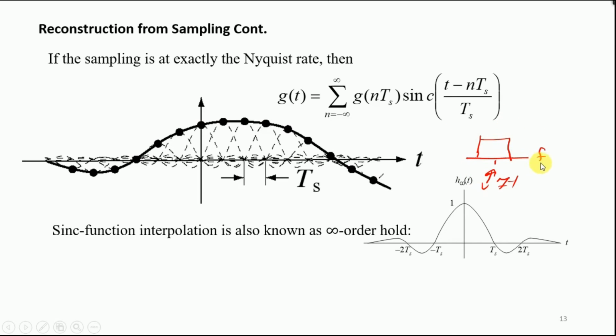By that, what we mean is, even though we have sampled at the Nyquist criterion, we would still lose some information. One way to improve the results is to have a sampling frequency much greater than 2W, right? For example, in our telephones, our voice spectrum is bounded to say 2.5 to 3 kilohertz, but cell phones sample our voice at 8 kilohertz.